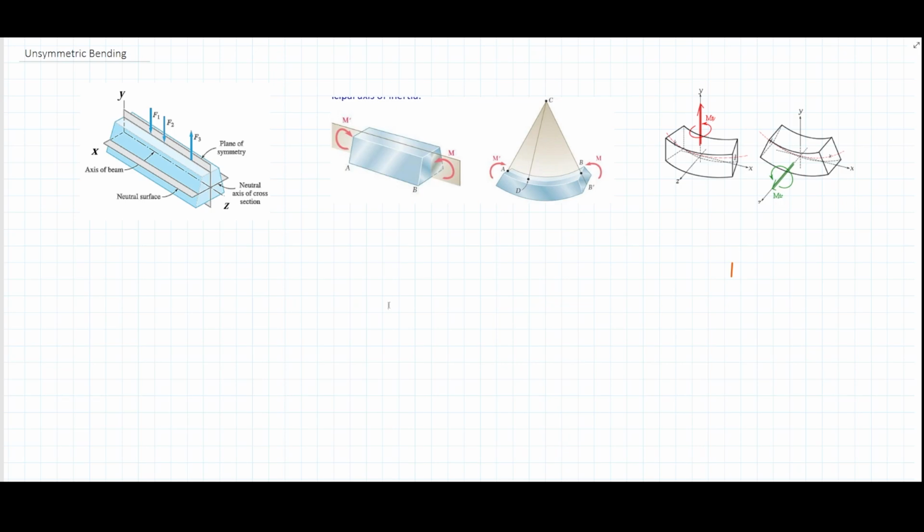So simple bending, the theory of simple bending, is something that I could write: the stress found in simple bending is the moment times the distance from the neutral axis to the farthest away point, divided by the moment of inertia. This is a formula you already know. Then that's going to give you a value of stress. And again, that's applicable only to simple bending.